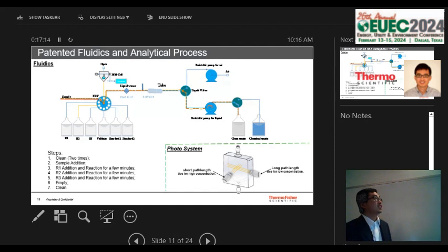So this is the section of the sample. The liquid sensor tells us this is a flow of liquid, and between here and here is where it determines how much liquid we are sampling, rather than relying on the pump, which can deteriorate over time. So this tells us we're always sampling, say for example, 5 milliliters of liquid, because it's a section of tubing. The section of tubing never changes.